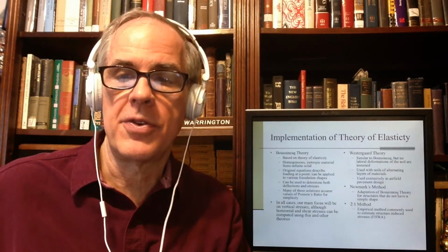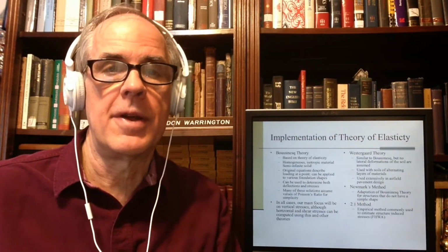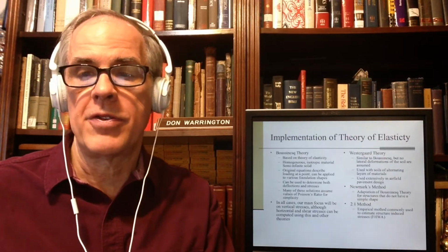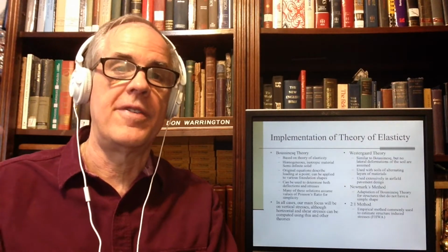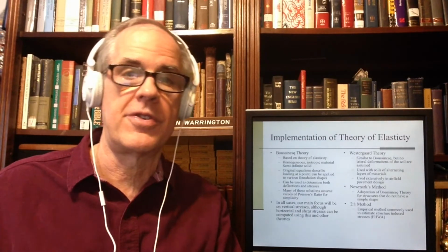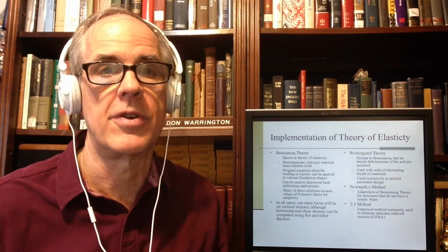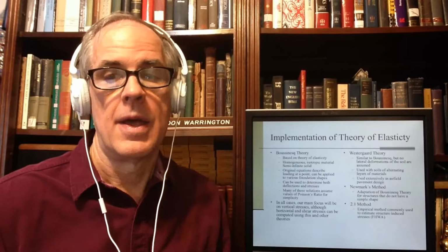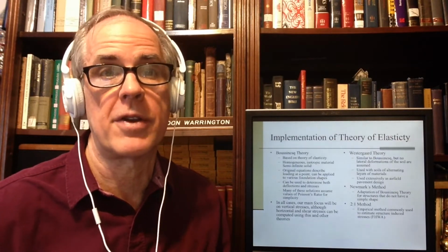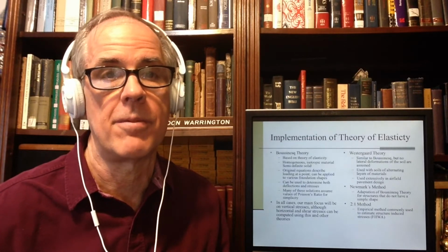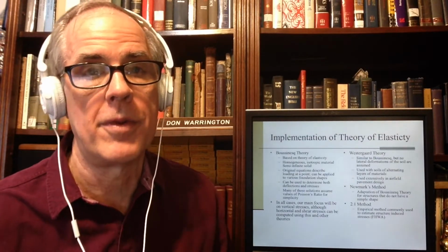Last but not least, the 2-to-1 method. It's an empirical method for stresses only, to estimate structure-induced stresses under the center of the foundation. It cannot be used for the sides like Boussinesq theory can. The FHWA pushes it. It's easy to compute, and the results for practical purposes can be very useful.